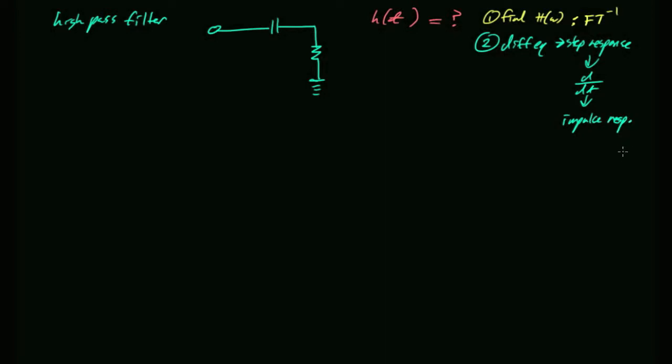Both methods will give you the same answer, because there's only one right answer. Which of these is least off-putting? First. Let's find out. Yeah, that's my shorthand for inverse Fourier transform. Okay, so what is the transfer function for this thing? Let's see, this is R. What's the impedance of that capacitor? 1 over j omega C. And so this is just a voltage divider, right?